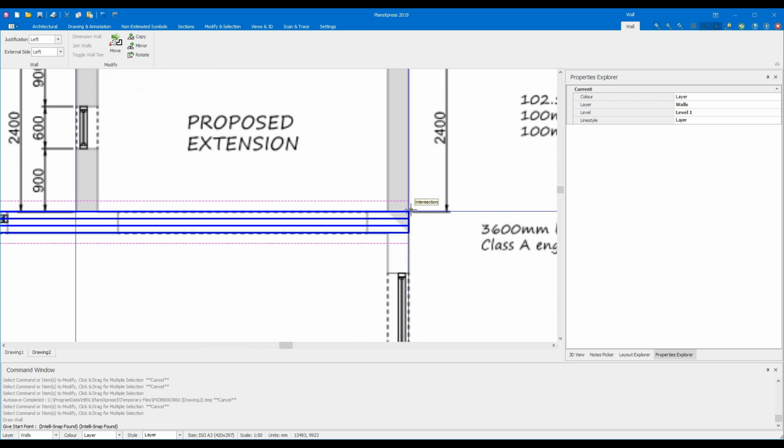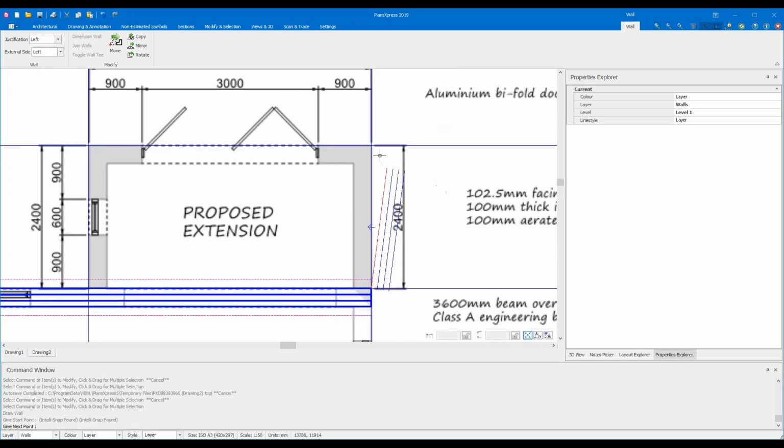there you'll locate maybe an intersection point, possibly an end point. I saw the end point pop up at one moment. It's actually the same point because it's the end of a wall, but it's also an intersection point of a couple of construction lines. So the same snap point might have multiple names. Once you've found that end point or the intersection point, click the left mouse button to place the start of the walls. Whenever we're placing anything on screen, we click and release the left mouse button. We don't hold down the mouse button at all.